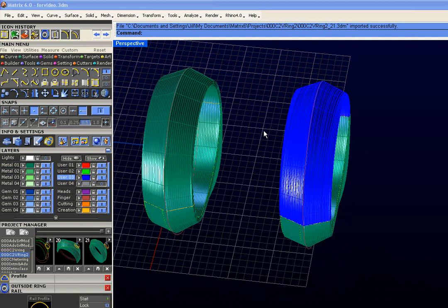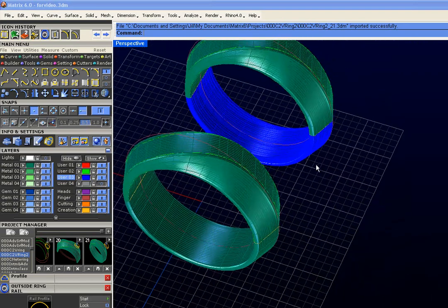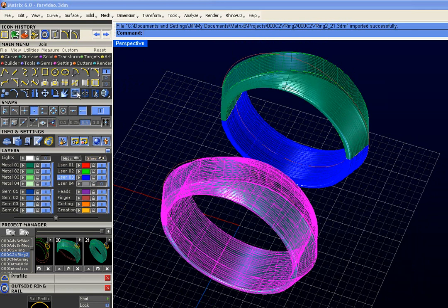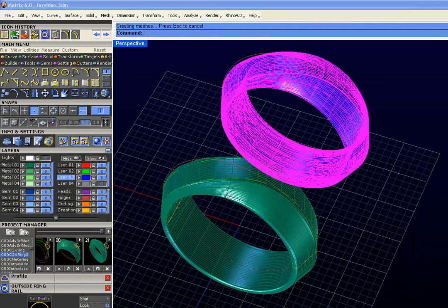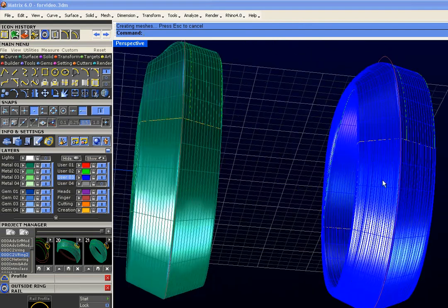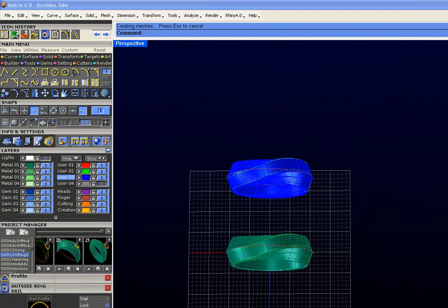Okay, so that's why I duplicated those profiles ahead of time, so that I wouldn't have to rely on the surface, which I knew would be twisty and interesting and give me some pretty strange results. Okay, we can still join these together into one closed poly surface, both of them, so you have the option of the twisting, strange shape on the bottom here, or sort of the more normal, regular one.